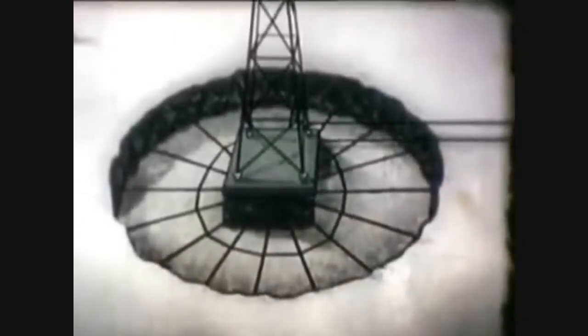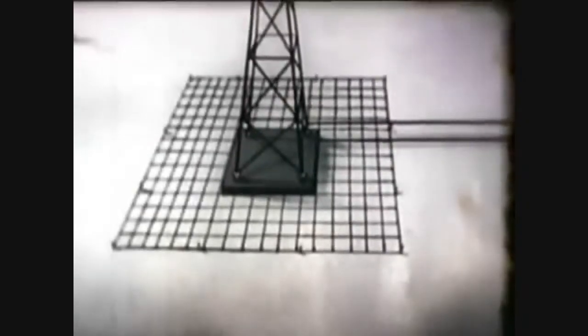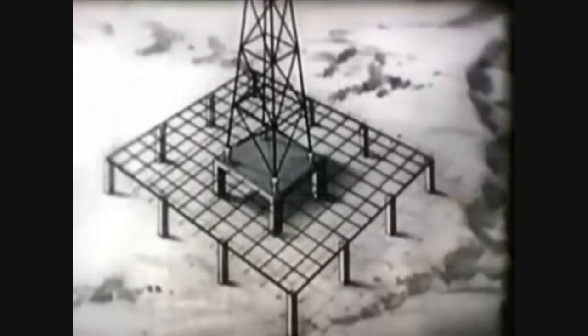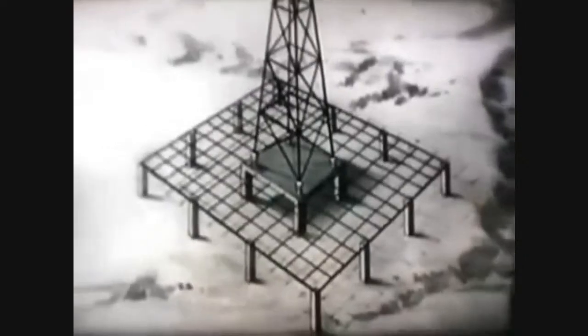At installations near the sea or in salt marshland, the Earth's conductivity is excellent, and a simple metal stake provides proper ground. In drier regions, a system of conductors installed at the base of the tower may be required. These radial conductors are connected to a common point at the base of the tower. Sometimes on some installations, an additional system of wires lying on the ground, called a ground screen, is used, thus forming a more effective ground. Where it is not practical to bury conductors, a network of wires called a counterpoise is built above and insulated from the ground.